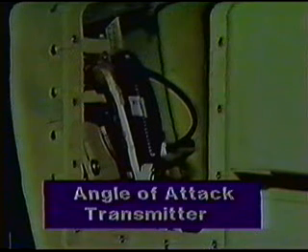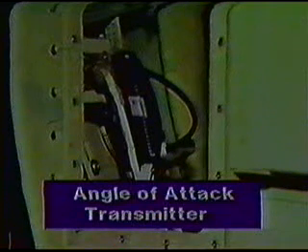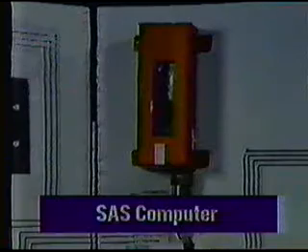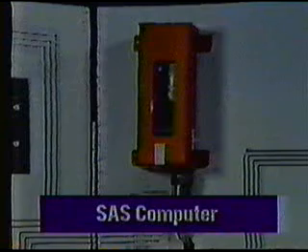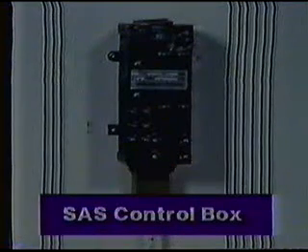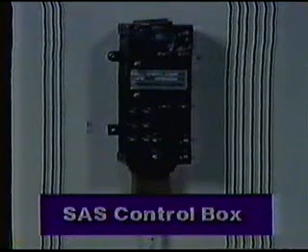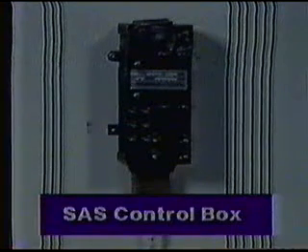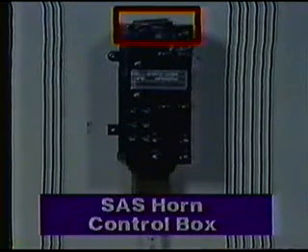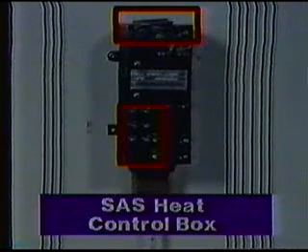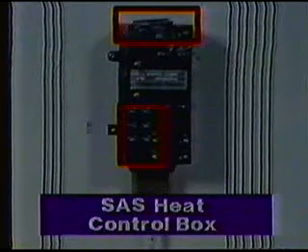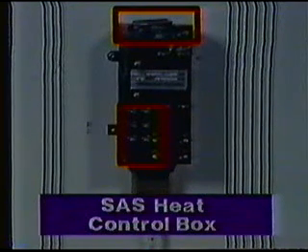Components of the SAS system include the unit mounted on the right-hand side of the nose section, which is called the angle of attack transmitter, or SAS vane. The unit installed in the right side console is called the SAS computer. The control box, located in front of the co-pilot's feet, is the SAS control box, sometimes called the SAS horn control box because it contains the SAS horn, and sometimes called the SAS heat control box because it contains components related to the SAS heat system.